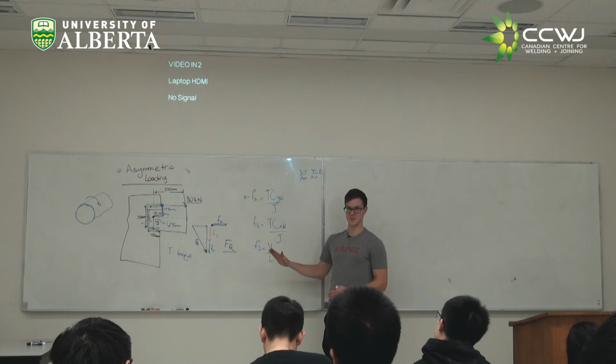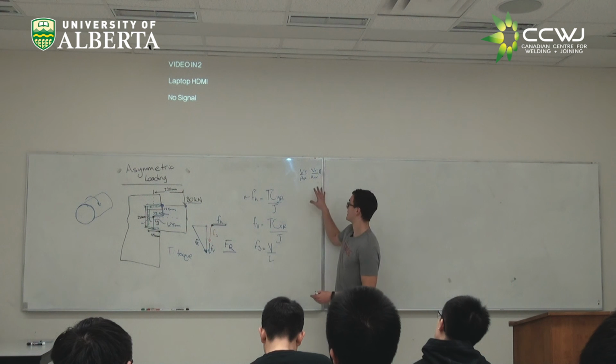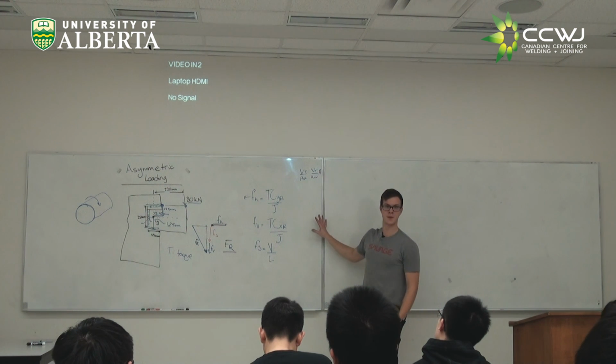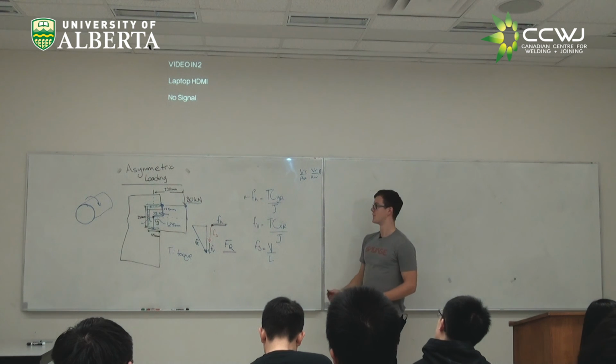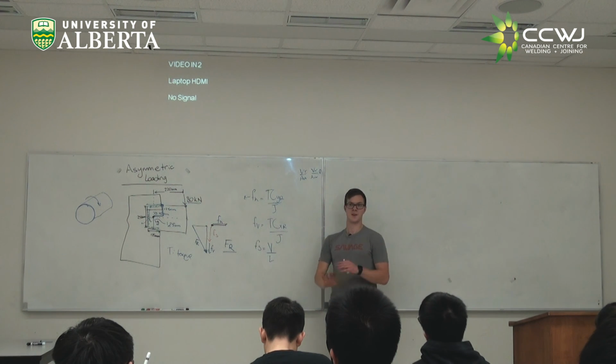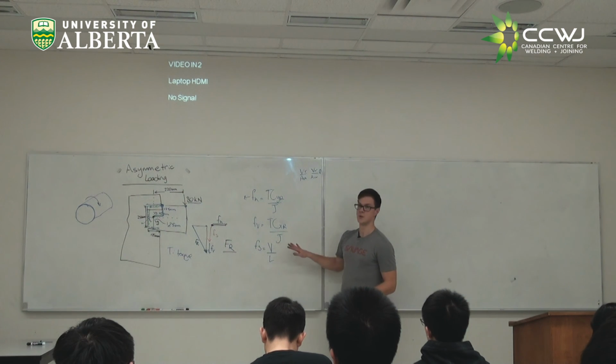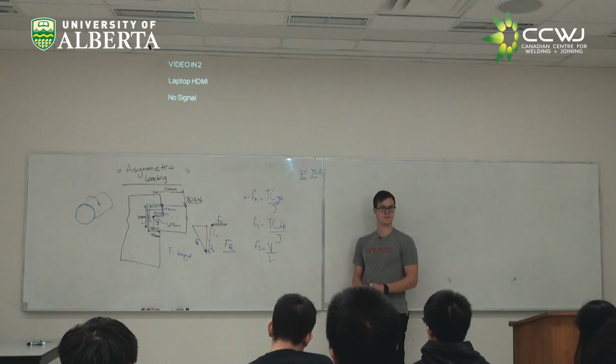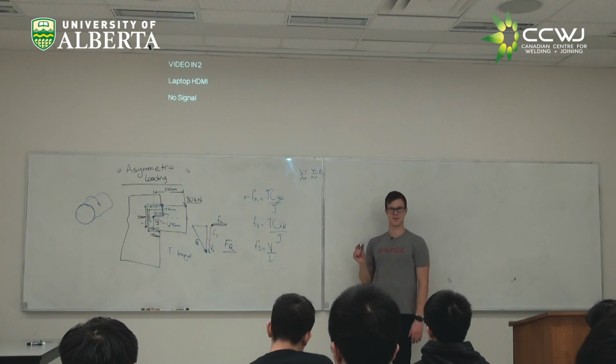If you have a situation where you have purely symmetric loads, and you may want to consider fillets of different sizes, using the first approach, where it just changes at the very last step, allows you to consider that. But if you want to deal with asymmetric loads, we're not going to add an extra layer of complexity to worry about different size fillets. So you can take the sum of the length, divide by that, and get your FS. Does that clear things up a little bit?